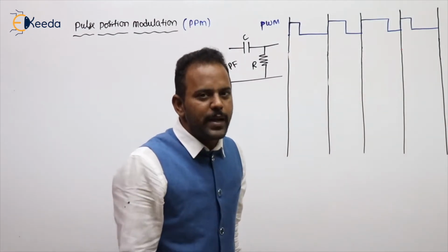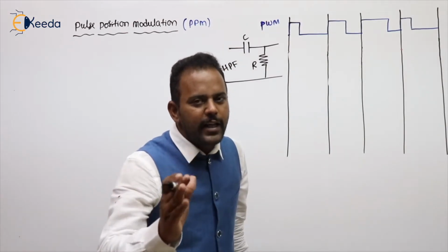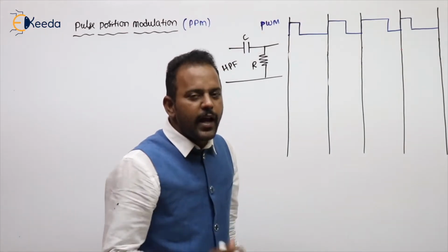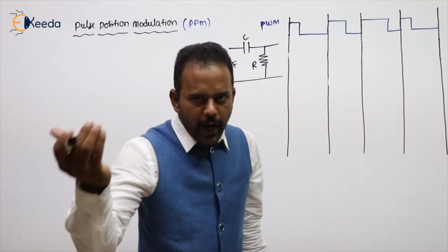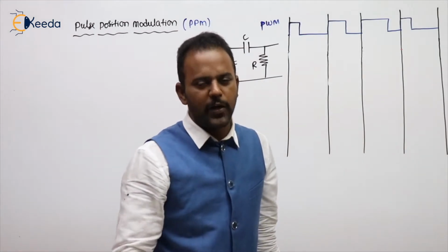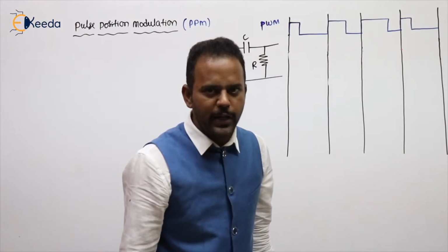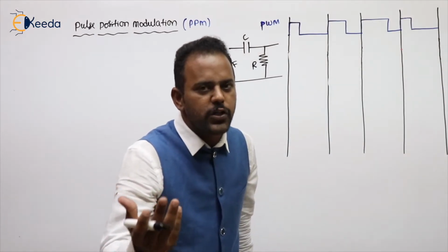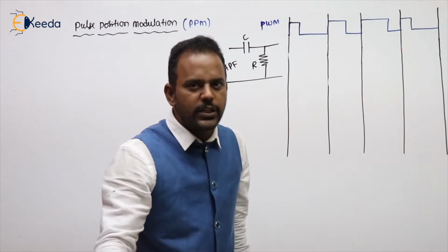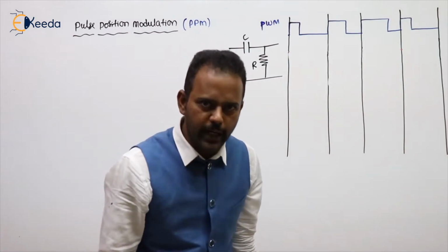You will get the impulses wherever there is an amplitude change. Amplitude change means final value minus initial value, right side value minus left side value. Are you following my point? If the change is positive, you get a positive impulse; if the change is negative, you get a negative impulse. Follow.